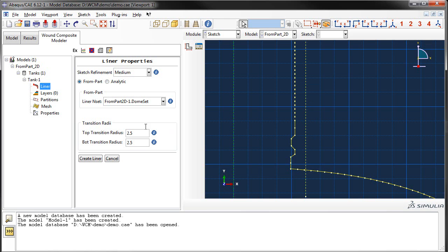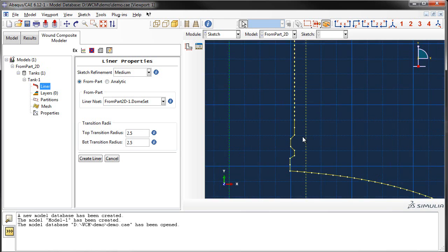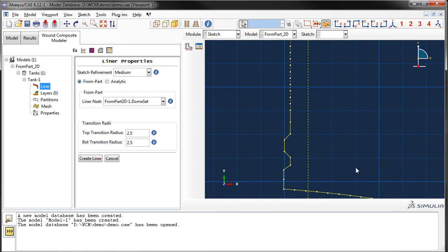Now the first step in that is defining this transition radius, which means that as a layer is building up and it's following those thickness buildup equations, follows them up to the point where it hits this transition radius. And then once it does that, then the slope of that layer, the outside of the layer, just remains constant until it finds an intersection with the polar boss.